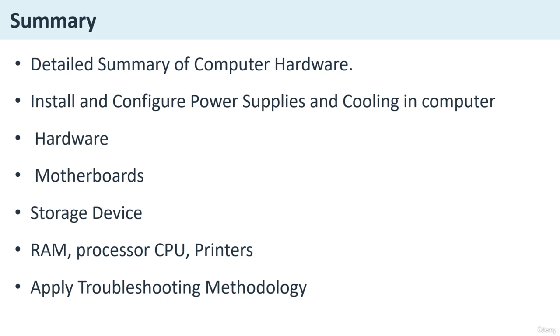Power supply testing. Paperclip test is the first one where you can test the power supply. Jump the green wire to any black wire, ground, to check if the PSU turns on. Second is multimeter test. It measures voltage output for accuracy. And the third one is load testing, using a PSU tester or software to simulate high power draw.